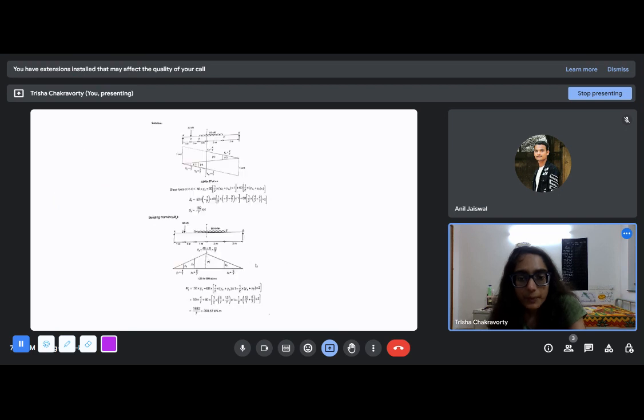So A into (L minus A) by L is 12 by 7. So this point is 12 by 7. And since these are straight lines, at 50 kilonewton, you can find this YC ordinate. It's found as 4 by 7. And we need the ordinates at this point and at this point as well, because again, we need this area.